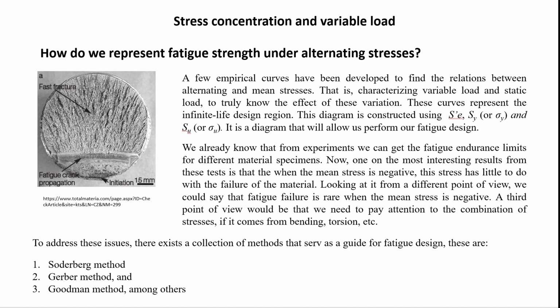I mentioned that later, but it's worth mentioning right now: damage in equipment is cumulative. As long as you're using a machine element in equipment, any damage induced in the machine is not healed when you stop the machine. No, the damage is cumulative, and that gives birth to other theories, such as Miner's rule for cumulative damage, where instead of considering that damage occurs only when it's working, damage is always accumulating in your part, and that is very complex.